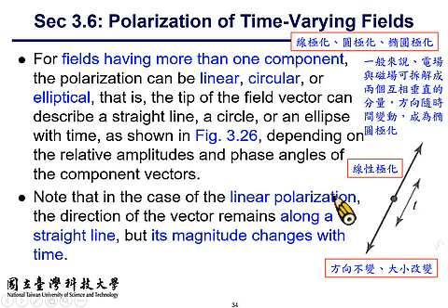Because in the wireless communication scenario, you need to have a transmitter and a receiver. And the receiving antenna should be what? Well, the general principle is your receiving antenna must have a polarization that is the same as the transmitting antenna. Okay? So let me explain this a little bit in detail. Say you have...